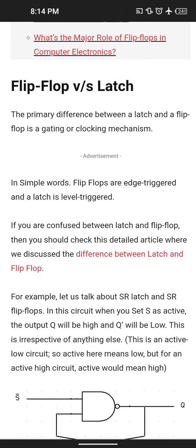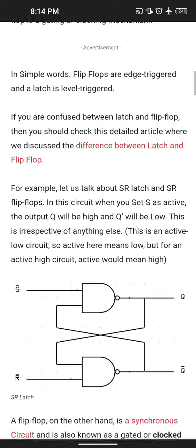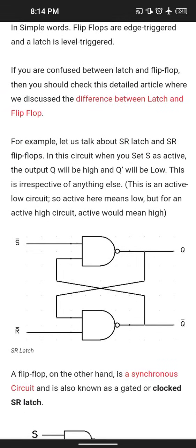Flip-flop versus latches. The primary difference between a latch and a flip-flop is the gating or clocking mechanism, in which, simply put, flip-flops are edge-triggered and latches are level-triggered. For example, let us talk about the SR latch and the SR flip-flop.